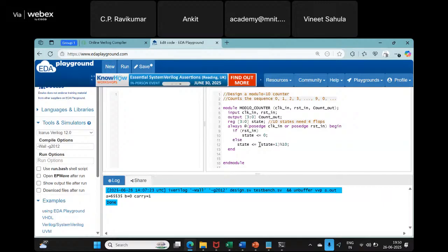See here, I am sort of using a behavioral assignment. Okay, I am not explaining how to design this. We need a circuit that takes a 4-bit number like state, increments it by 1, and then takes the modulo. Okay, that circuit I am not designing. Okay, so if you want to design that circuit, you have to do it yourself, if you are not willing to leave that to Verilog.